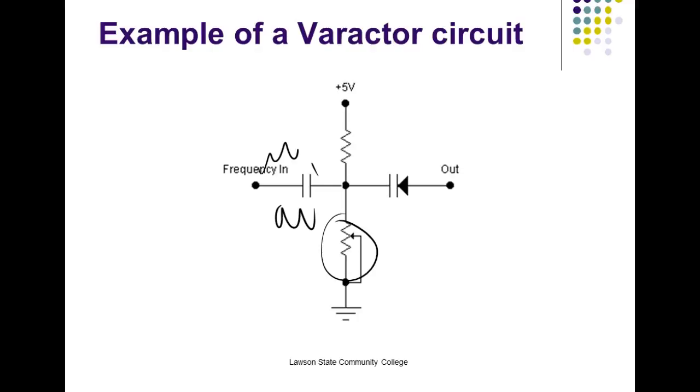There's a more precise circuit now we call a phase lock loop. Most of your radios use phase lock loops now. The problem with these guys is they drifted with frequency. Have you ever tried to restore an old radio? The channels constantly drift on those, so you're constantly on your what? Tuning them up. You had to do that on your TVs too. Everything we had a fine tuner on it. TVs had a fine tuner on it. Because what was happening is we were using these tuned circuits that were affected by what? By temperature. Semiconductors are affected by temperature.